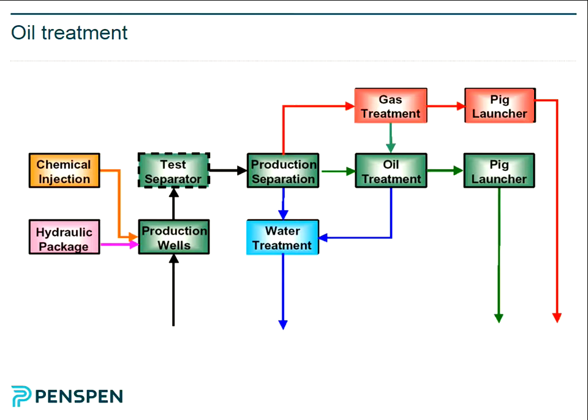So these are reducing pressure: high pressure, medium pressure, low pressure, and the gas goes off to your gas processing, or in some cases it'll be a flare. Less so these days, but certainly used to be the case. The gas was disposed of, and when I worked offshore, it was disposed of. But now they tend to collect it and compress it and try and use it as a product. And eventually you get, the eventual product is what they call dead oil.